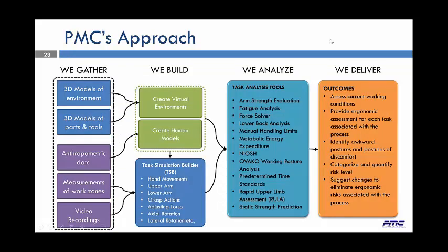So when PMC approaches a project such as this, we look at everything that we have and gather the information. We gather 3D models of the environment. If they're not available, we'll create them. We create 3D models of the parts and the tools. Once again, if they're not available, we create them. We gather the anthropometric data, the measurements of the work zones, and then we also do video recordings of every